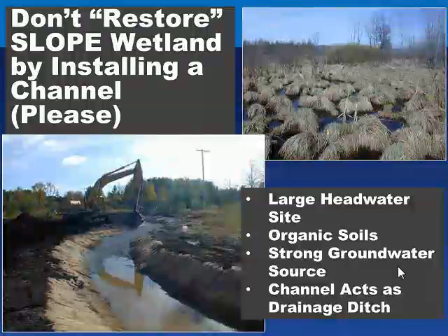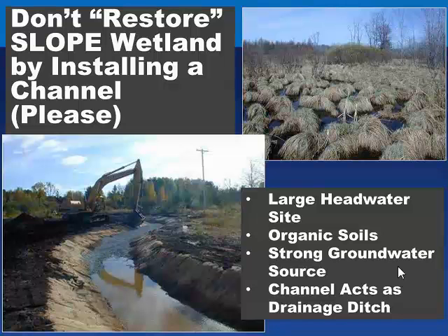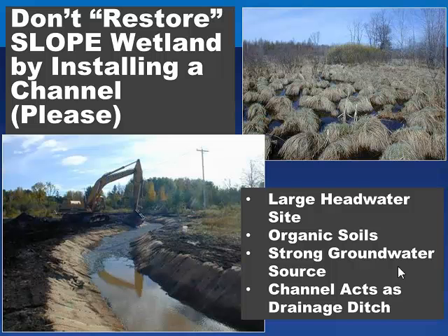In an extreme case, I'm going to direct you to look at the slide in the upper right-hand corner. This is a very large-scale slope wetland, surface saturated. We're at the peak of the hydroperiod in early spring. We've even got some nice hummocking, tussock sedge dominating the site. Really good, highly intact slope wetland, taking large amounts of groundwater and releasing it downstream to larger reaches in the